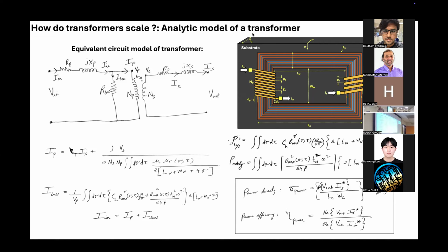But if you look at the density of the distribution, the density here is very low compared to here, which tells you there's a very restricted number of designs that satisfy the requirement, right? And if you look at what is needed to meet the requirement, it again comes down to materials. In order to get this requirement for doing a direct 48 to 1 volt transformation, you need a magnetic material that has certain specs, like permeability more than this, a certain resistivity and frequency of operation, right?